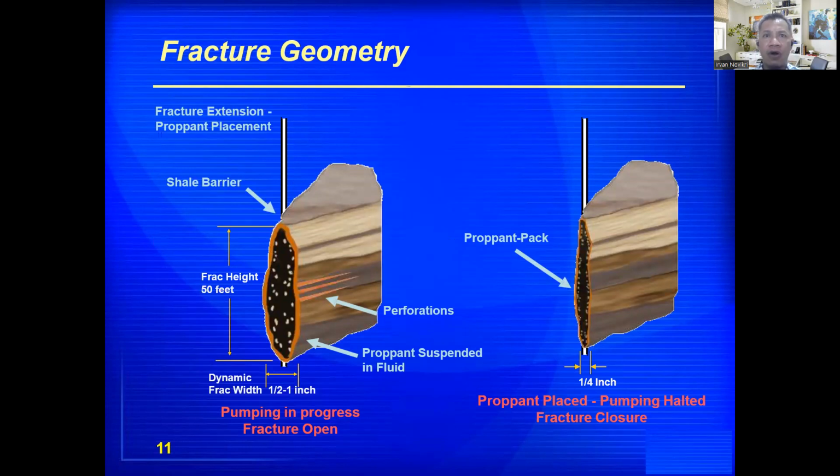The reason for that is if the proppant turns into the corner, gravity will take over. And this is why when we are trying to get this along the frac in tight sandstone, like the Mesa Verde or Travis Peak, Cotton Valley, something like that, then in that case, you've got to have the viscosity to carry the proppant out several 100 feet from the wellbore. Without it, it will fall out. In shale, it's a little bit different.